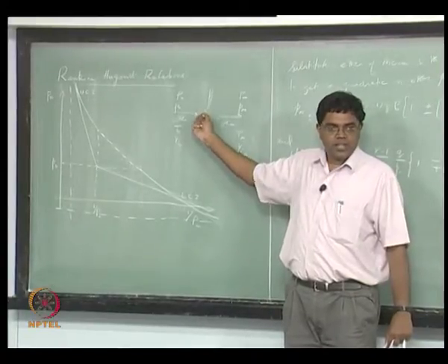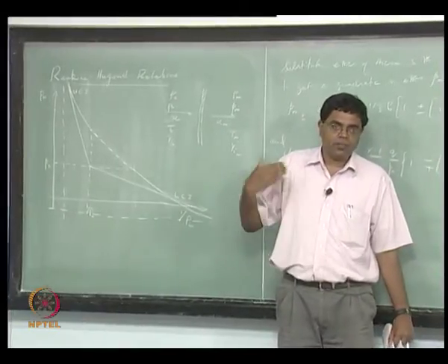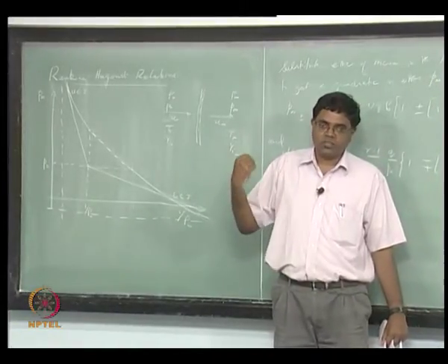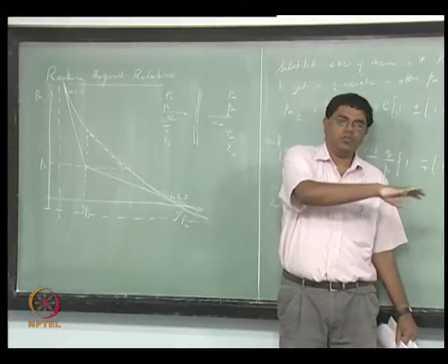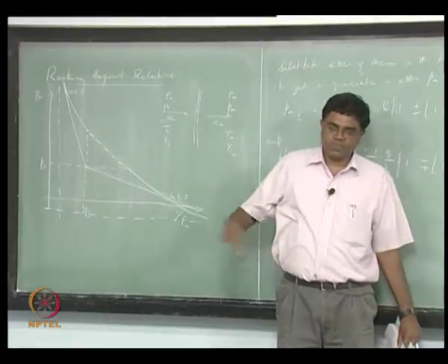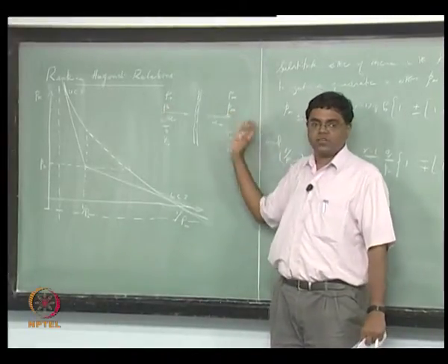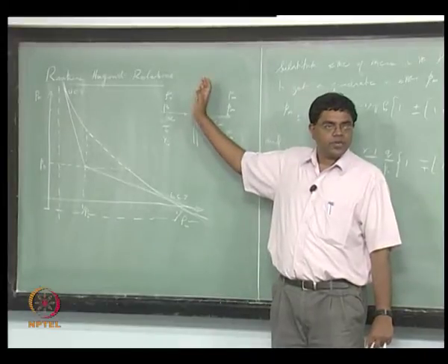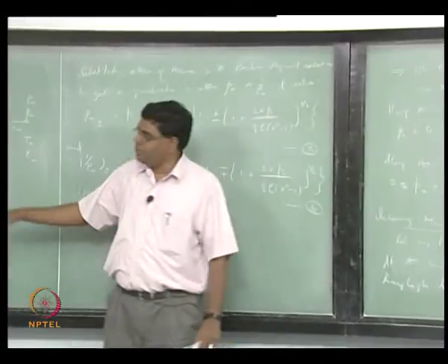and that information is now in our scheme of things embedded in m dot, because m dot is the one that's containing rho naught u naught as well as rho infinity u infinity. So it serves the purpose of carrying the flow information on either side of the wave, right. And since we are actually looking at the incoming Mach number, we should be focusing on u naught.